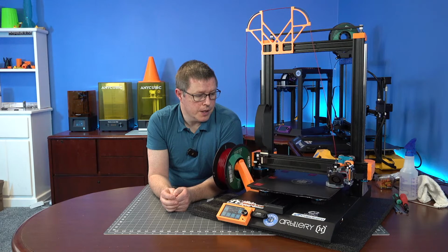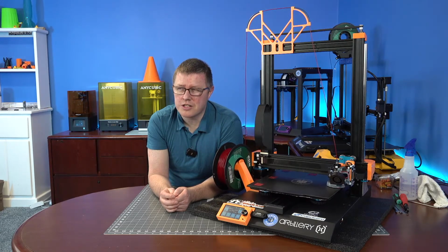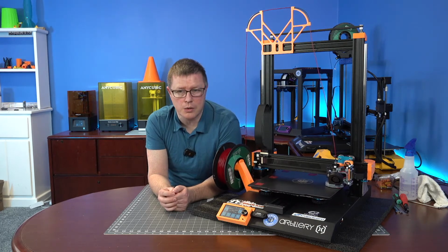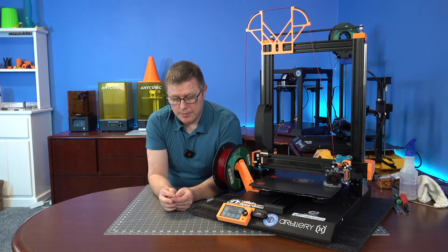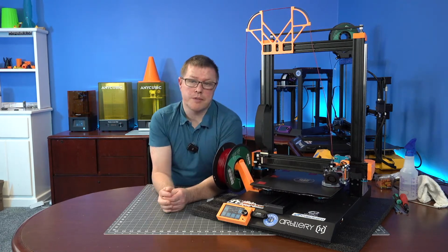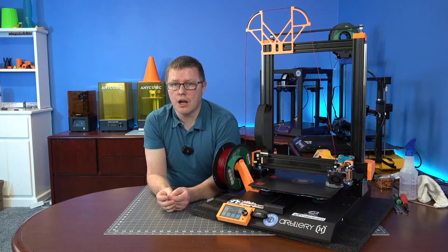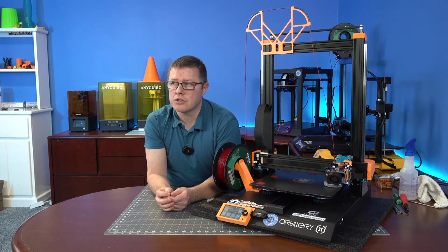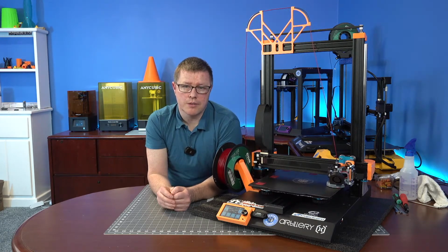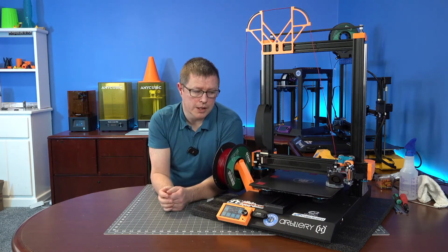And on this I have an acceleration at like 400 or 600. I think 400 for when I want to print nice things and 600 when I want to go a little faster. If I want to go really fast, I use the SP5 because I have that at like 1500 for the shells and 2000 or 2500 for everything else, and it prints real nice and real fast.